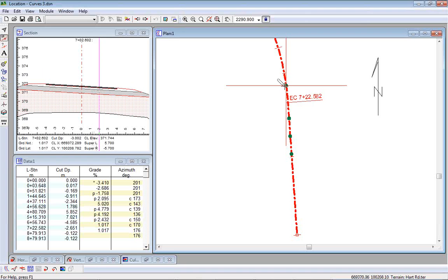I forget those terms all the time. Anyway, that's where it hits maximum super elevation, and then it continues at maximum after that point. So that's valuable information if you're trying to figure out where things happen. If, on the other hand, you're just reporting cross sections, all the super elevations are well defined, so they're written right in there.